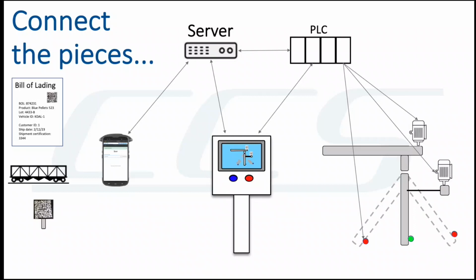of the project and just do some minimal interlocking to prevent maybe the unloading motors from starting and monitor the limit switches. If the customer doesn't have an HMI, that could be part of the project. It could even be a web app. It doesn't have to be a standard OIT or HMI program. It could be anything. So all of these questions depend on what the customer has now and how much they want this system to do? How many features and how much integration with their existing system?